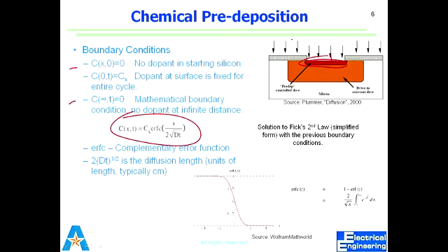So pre-deposition is high concentration, high temperature. The idea is to get the dopant across the boundary from gas to solid silicon. Once you get in, then we just drive them in. Right? So this is an error function which is defined by a certain integral. The idea is that as we increase the distance and time, we get a certain profile which is not linear.